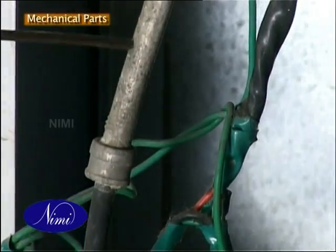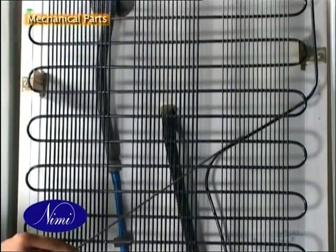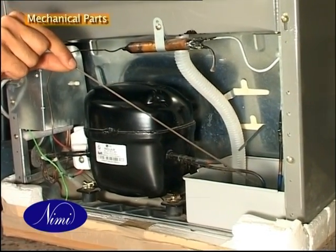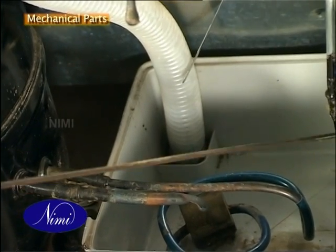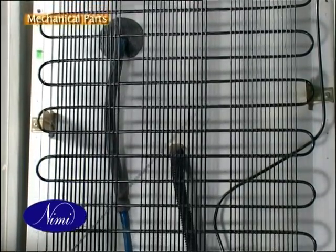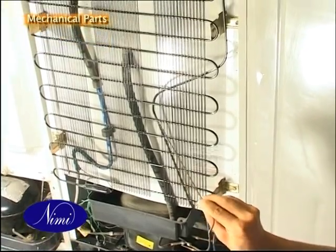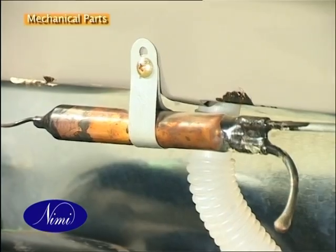Suction line. The line through which refrigerant flows from the evaporator to the compressor. This is toward the low pressure side of the system. Discharge line. The line between the compressor and the condenser is called discharge line, which is towards the high pressure side of the system. Condenser. Condenser works as a door to discard the heat absorbed by the refrigerant at the evaporator, plus the heat added at the time of compression, and the refrigerant gets liquefied.